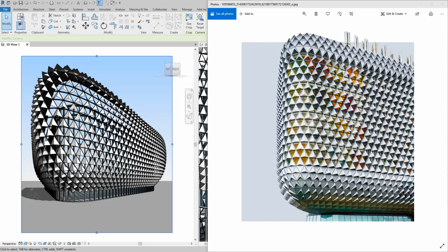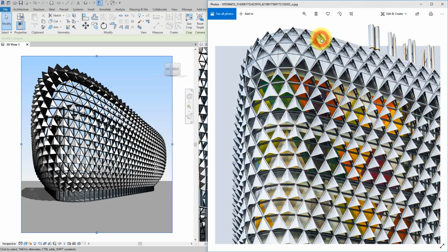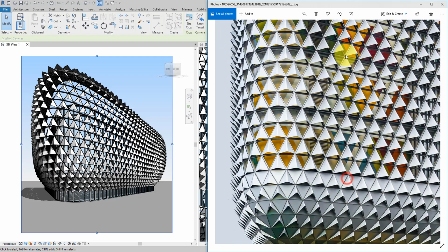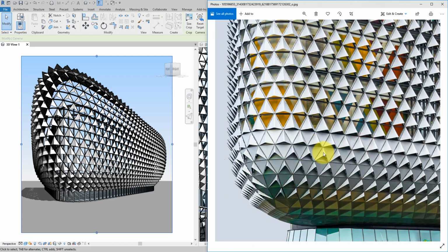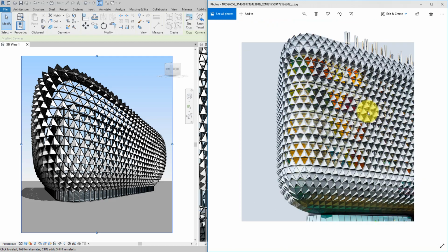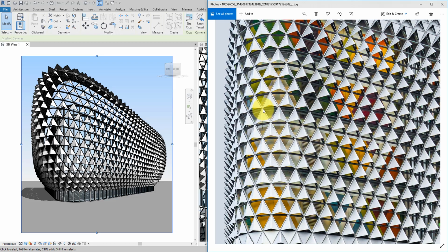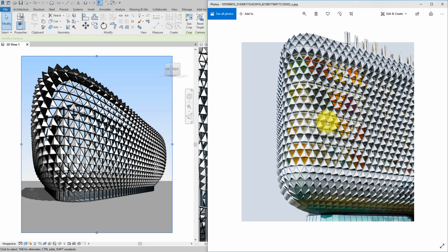Today, let's do some conceptual modeling. I will show you quickly how to create in your Revit file this kind of facade system. It includes metal panels. Some are open, some are closed. The closed panels are mainly on the top floors and the bottom section of the facade, and wherever else you have open panels, so that when you look from outside, the content of the building is visible. If you want to create something like this for your project, this is the video for you.